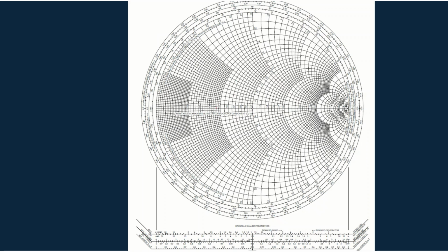We have seen that here comes the constant resistance circle. So this is my 0.5. I have to note this constant circle, and then 1j. I have to look for where the 1j comes. So this is the inductance marking. Here you can see 0.1, 0.2, 0.3, 0.4, 0.6, 0.7, 0.8, 0.9, and 1.